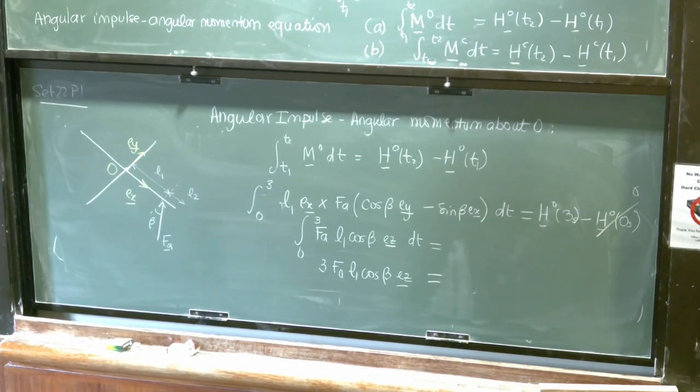If I were to look at the four-door panel, you can think of them either as 4 rectangles or 2 big rectangles. So I'm going to use the parallel axis theorem. I'm going to use the fact that the moment of inertia of a composite body is the sum of the moments of inertia of each of these bodies. And I'm going to use the tables. So let's open up the tables.